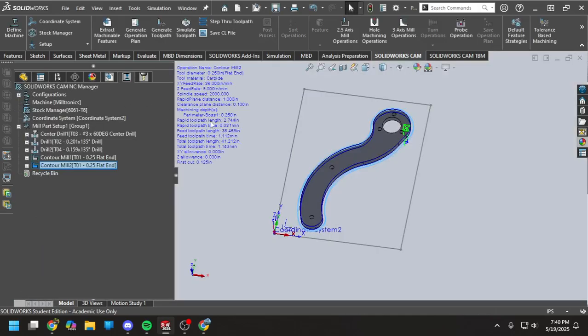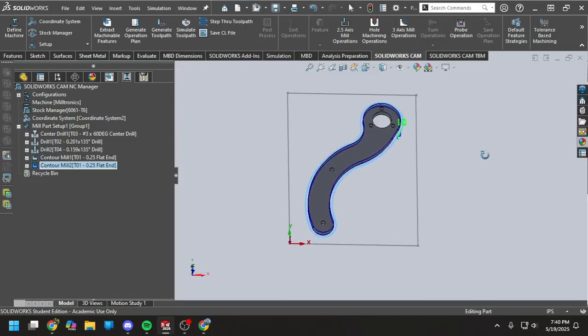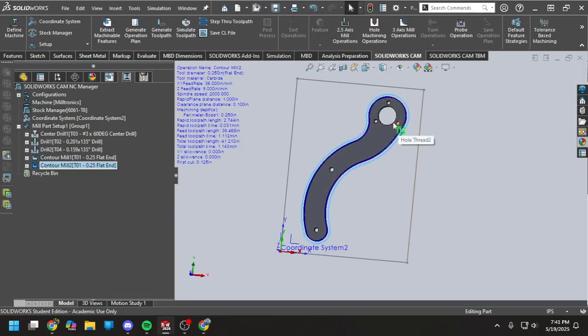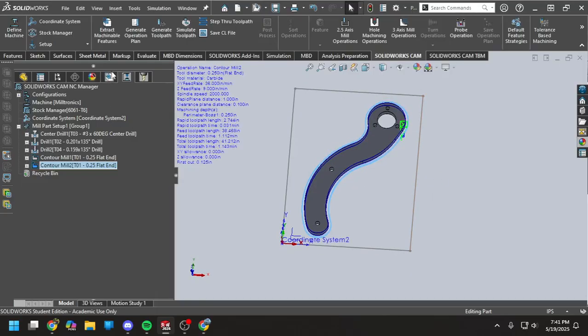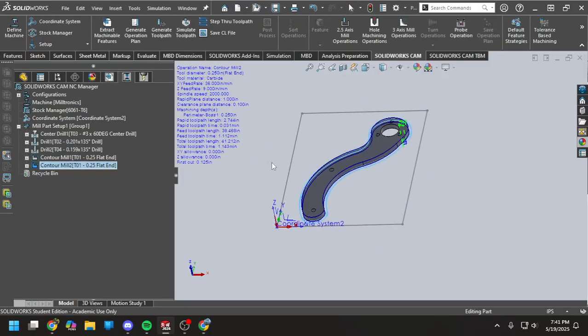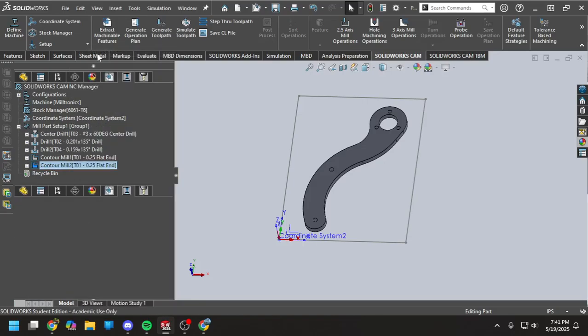So there are 2 options. If you're clamping this on top of a sacrificial board and you're not holding this in the vise, you can screw the part directly to that sacrificial board using the holes you drilled in an earlier operation. Just free holding the machine, throwing some wood screws in there, and sending it on its way. However, because we defined this as a perimeter boss instead of just a regular pocket or something like that, we can edit the definition of that contour mill.